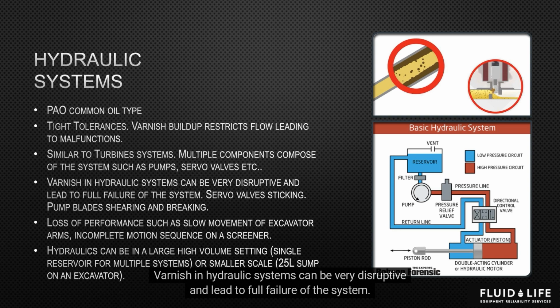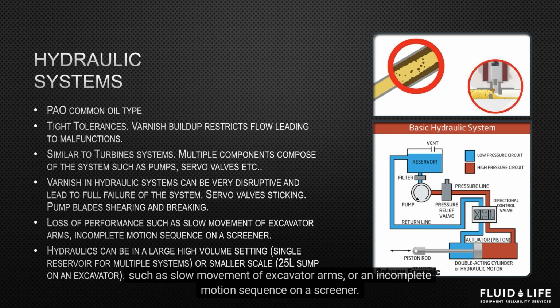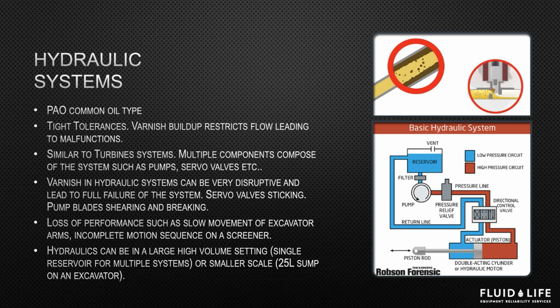Varnish in hydraulic systems can be very disruptive and lead to full failure of the system. Some effects of varnish include sticking to servo valves, pump blades shearing and breaking, a loss of performance such as slow movement of excavator arms, or an incomplete motion sequence on a screener.